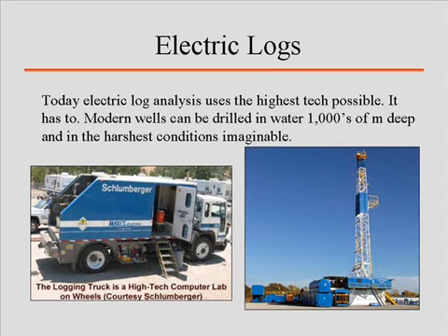And what they do is they position the next pipe as they're getting to a certain level below it, they more or less just put chains around it to guide it down. And then they will put the male thread, they'll catch it here, it will tighten up, and then you're supposed to let go of the chain. In fact, the difference between a good roughneck and a bad roughneck can be determined on a handshake. Good roughnecks shake like this, bad roughnecks shake like that. Okay? Because if you don't get your fingers out of the chain fast enough, you lose your fingers.